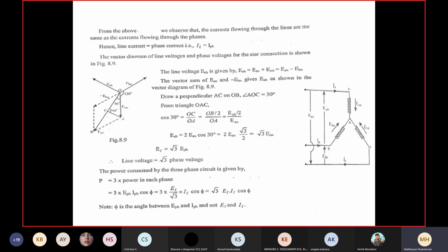Then what is the single phase voltage out of that? 440 volt divided by root 3 I should do. That comes to 239 or 240 volts, what the single phase domestic user gets. That is the advantage of the distribution system being in star fashion. It can provide three-phase power or it can provide single-phase power. Therefore, there comes a relationship. That is the star connection.